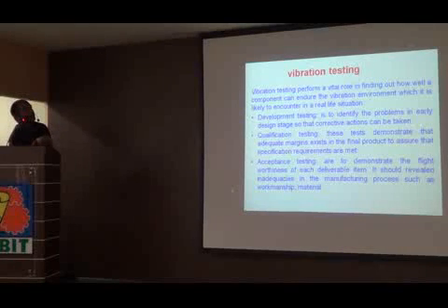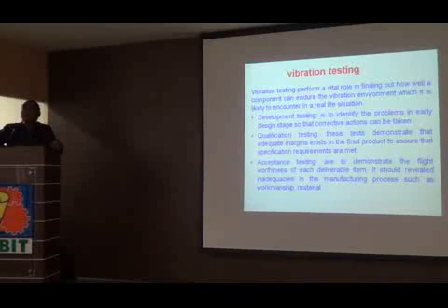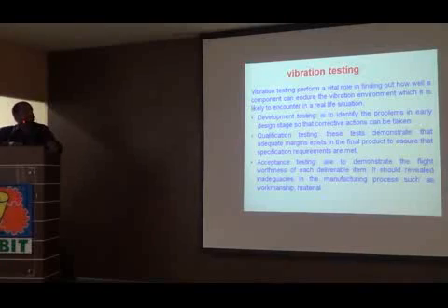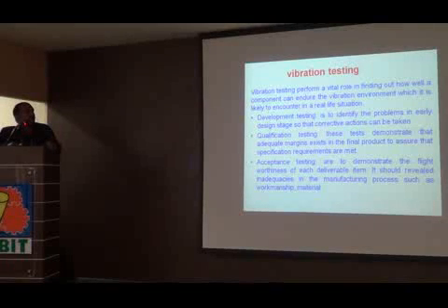Right now I will focus on vibration testing. Why do we do vibration testing? We do it for just two things. One is to check the structural integrity. Like the last missile, when we checked, it failed because one of the structures did not have the same strength as the coupler. Such situations we can avoid beforehand by doing this vibration testing.